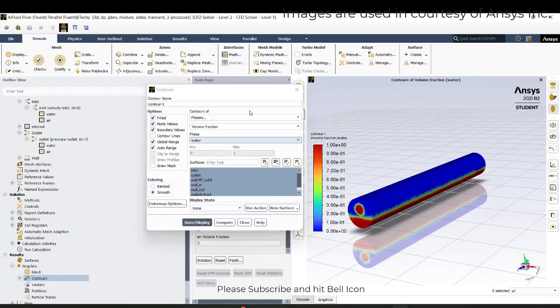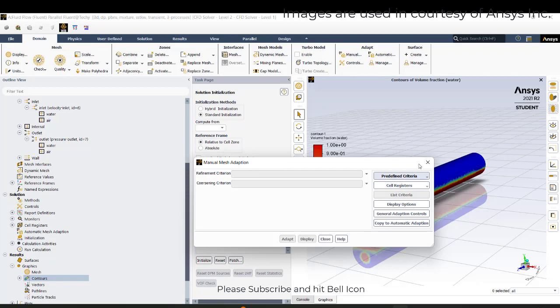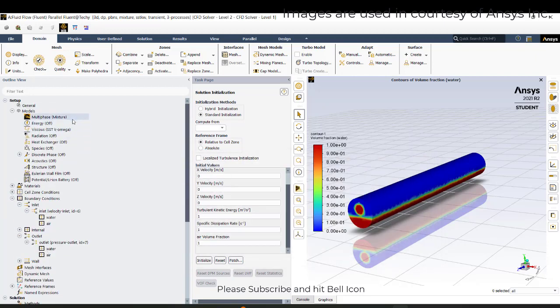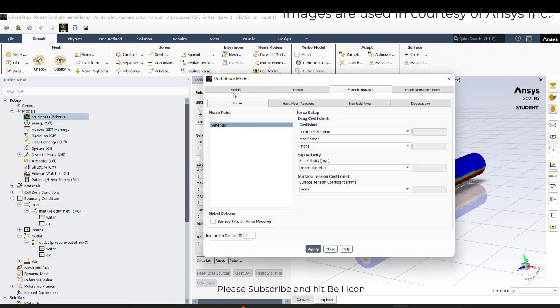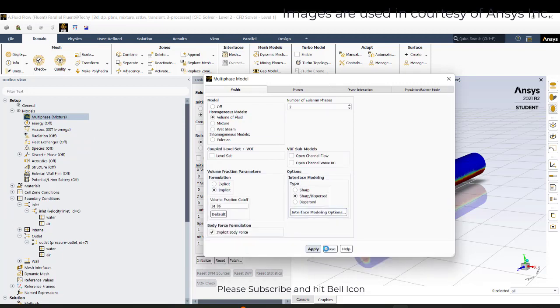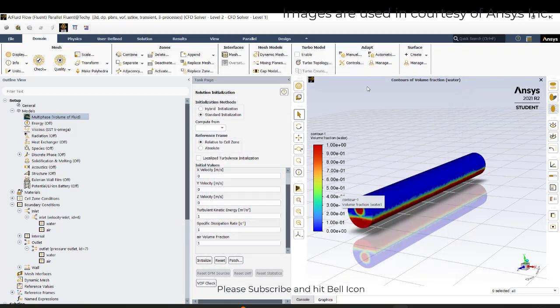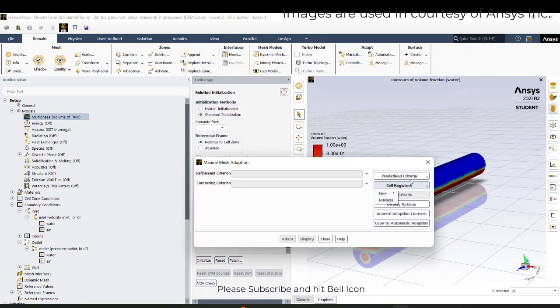So now we can also have an adaptive refinement. We'll just try to show how to do the adaptive refinement. First, for that purpose, you can just go to the mixture model and use the volume of fluid scheme, apply. I'm using this volume of fluid advantage for adaptive refinement. In the predefined criteria, go to volume of fluid.